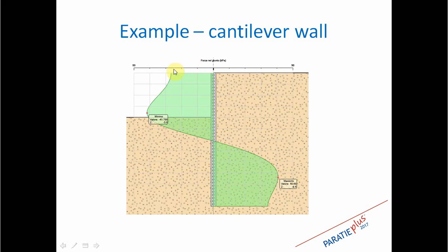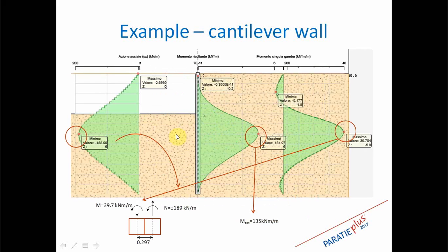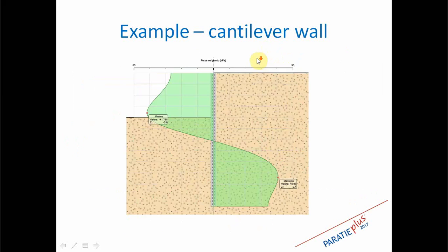And here we have the distribution of shear force along the joints. Of course, we can see that more or less, this complies with the shear force distribution like a beam, because here we have almost a zero shear, and here we change in sign when we have the maximum bending moment, as said by normal theory of structures.